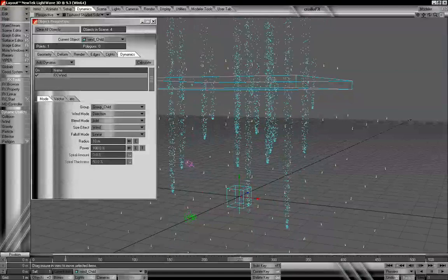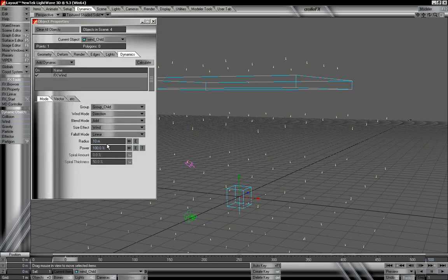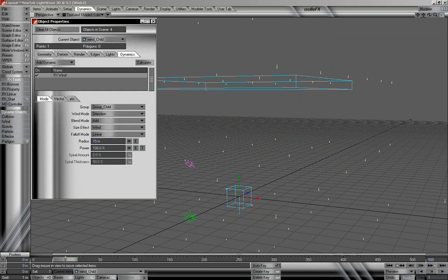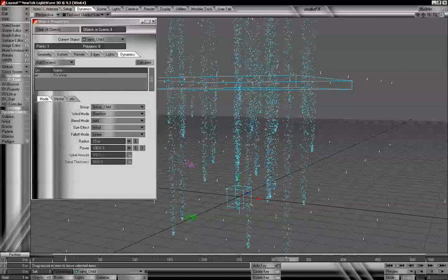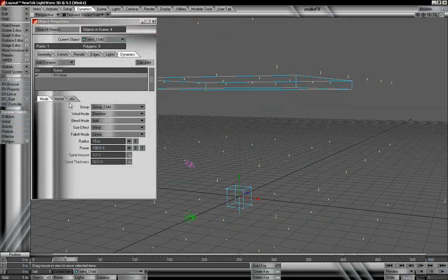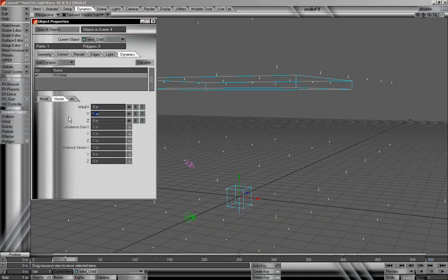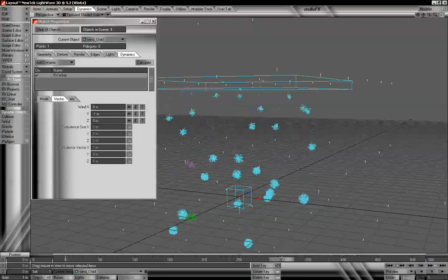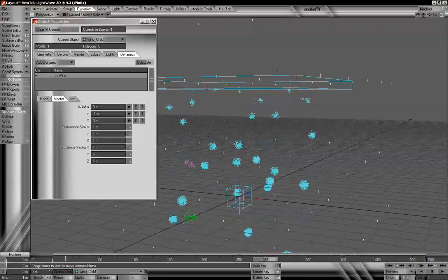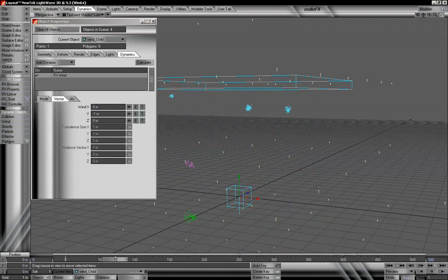And we end up with a fairly interesting looking effect. I'm going to increase our radius a little bit more, up to 15 meters, so we can go beyond the normal values. For right now, we have this set to direction, so I could change this to a -1 on the Y, and now we're going to be blowing our particles down. And we can see it looks a little bit different, because it is now matching somewhat with our gravity, and it's kind of spraying out our particles and creating little bursts, which can be a really neat effect if that's